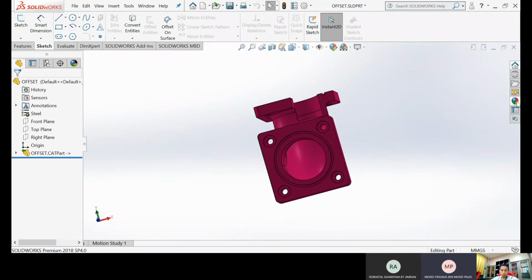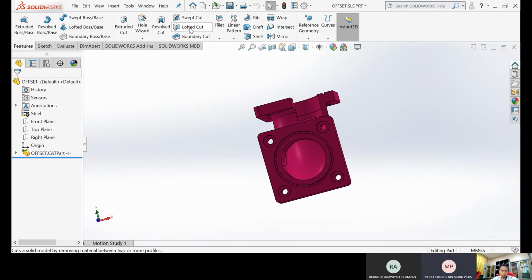Then we can use the extraction option, which extracts all the surfaces according to the separated color surfaces. Then we extrapolate that information so that it can figure out how the surface can be created. Next, part 6 is trim and blend. The trim tool is used to remove unnecessary material and cut everything away from all the surfaces. By creating pocket geometry, it can be detected that the colors painted during the guided creation process were blended together. Create a boundary surface so that everything will look very smooth.